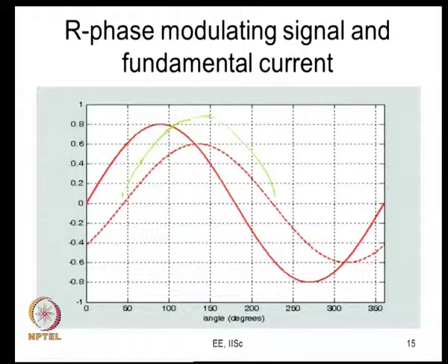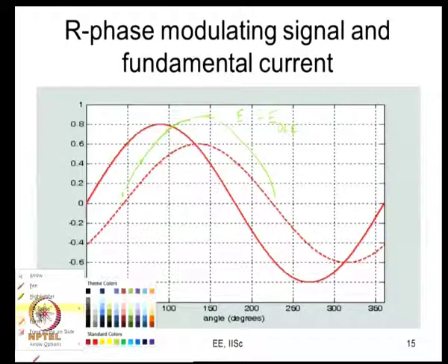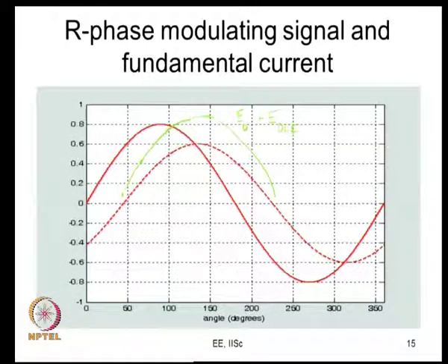So, what is it that I have plotted? I have plotted the switching energy loss. You can say that this is E on plus E off. During a turn on, it is going to have a certain loss, which is called E on, and during the turn off, it is going to have a certain loss, which you would call E off. So, this sum of E on plus E off is for one switching cycle. But that, let us say, varies like this.